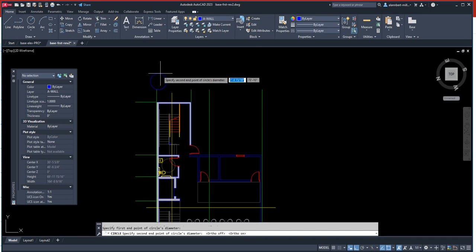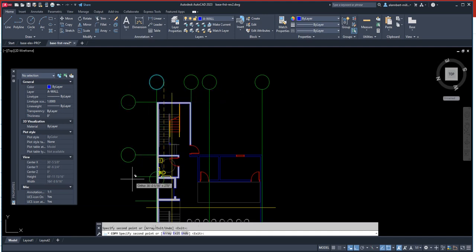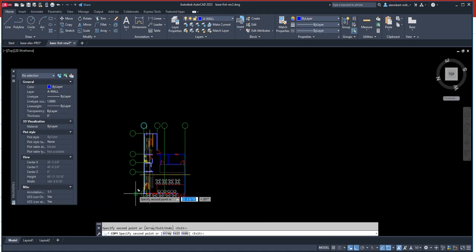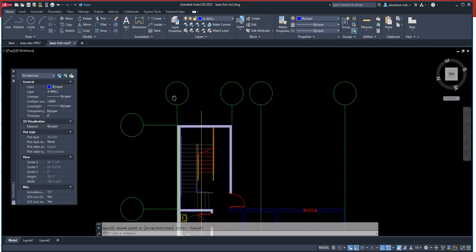Now let's click this and draw. And let's just make it a 1/4 inch, or not a quarter. This is model space, so let's just make it like this, and then match property so it becomes one with the grid. And I'm going to move this quadrant, say here, and then just make copies. Same thing here. So you have your grids and bubbles reference, and now you're ready to put in your numbers and text.